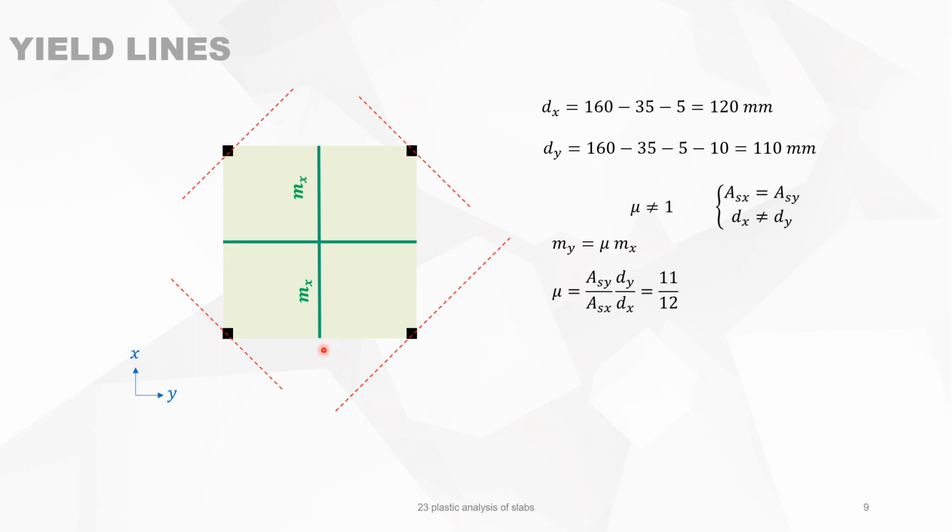We call this direction X, you can also call it Y, it doesn't matter, it's the same. You call it X, and the other direction Y, and then we can calculate E and D. E, the external energy. Well, it's simple because it's all squares, so it means it's the total surface of the slab multiplied by its load Q, which is not known yet, and multiplied by the mean deflection, which is delta over 2.